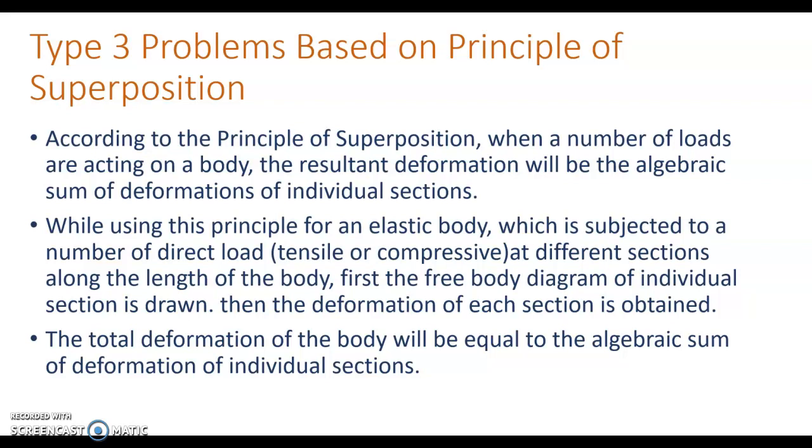It means that this principle is applicable when the body is in the elastic stage, which obeys the law that stress is directly proportional to strain. And the second point is that the body must be in equilibrium; only then is this principle of superposition applicable.